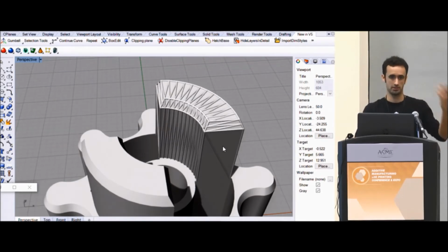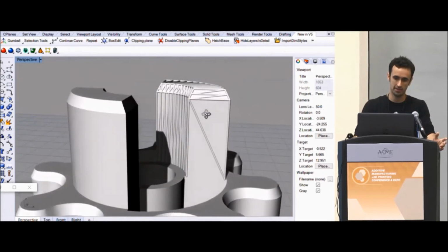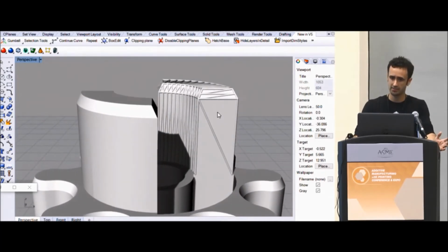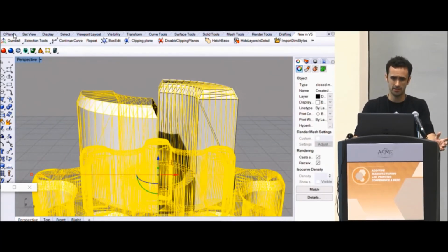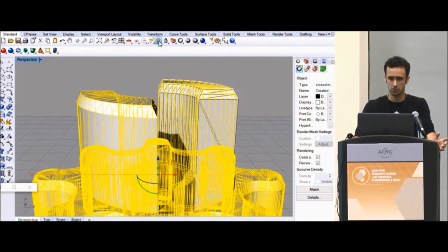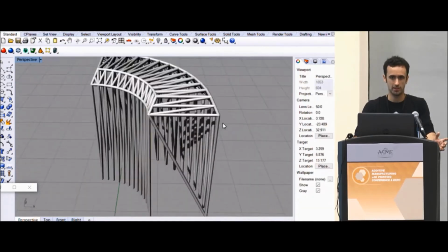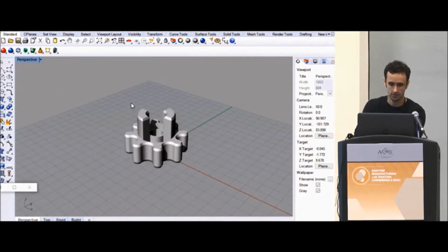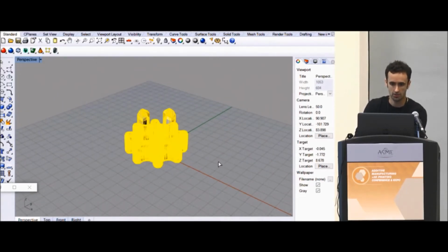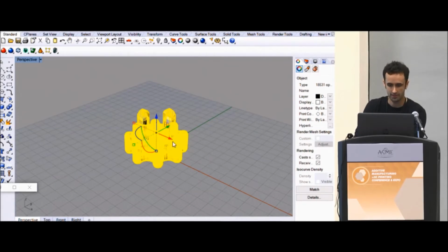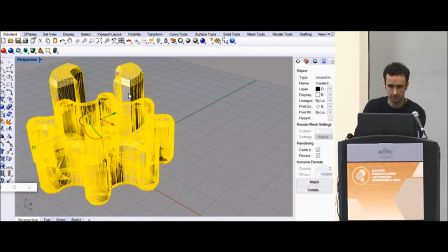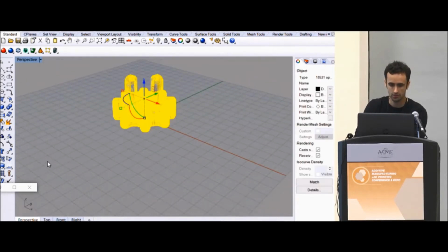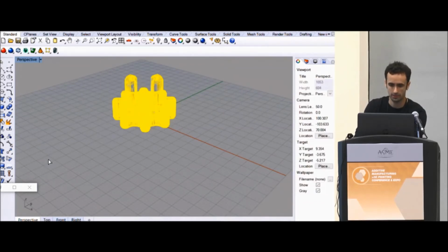in that I can control the tessellation of the object through different techniques of mesh reduction, or basically refining the topology. A lot of times I'll see stuff that looks like that, and they'll call it topology optimization, and no, that's just you piped the edges of your mesh. But you can do that to the whole object. I could duplicate edge to the whole thing, and then hide it and go pipe at 0.1.